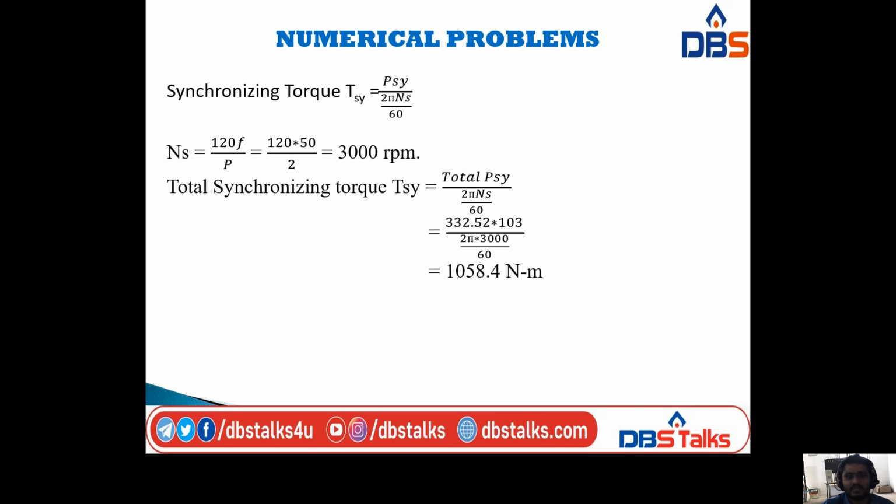Next, the total synchronizing torque is equal to the total synchronizing power divided by the angular frequency, that is 2 pi Ns by 60. The total synchronizing power we just calculated for the three-phase system is 332.52 kilowatts, that is 332.52 into 10 cube, divided by 2 pi into the synchronous speed 3000 divided by 60. After simplifying, we have 1058.4 Newton meter. This is the total synchronizing torque for the given system. Okay, this is the solution for the first problem.